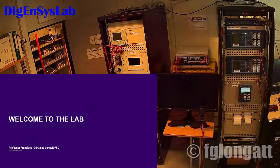Okay, what is the first test? The first will be the instantaneous, or we just put the definite time. We will set the pickup current, then the time delay, and we will see it.